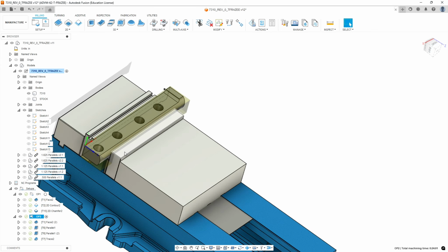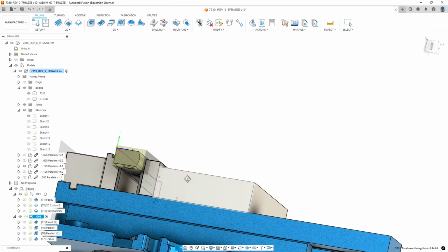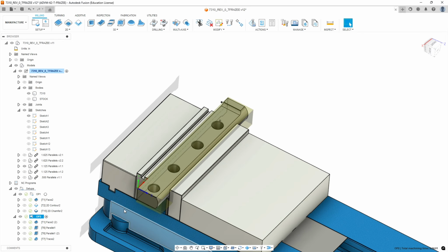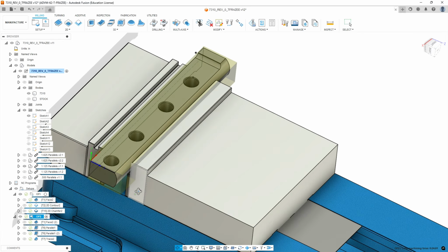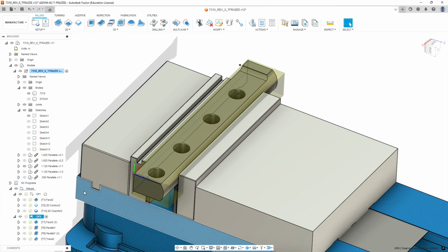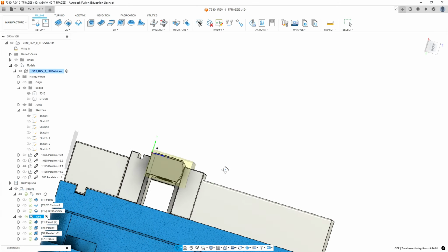The 1 5/8 are the tallest we have. There's one set at each machine. The other parallels are in a set in a red box, and you'll have to ask for them. We're going to keep control of that so we can double check your work. And so we should be using the 1 1/8 parallels.